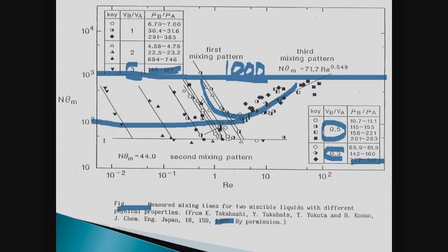It's 100 revolutions or 44 revolutions. So you're running at 1,000 revolutions, you improve your geometry. Now you're at 100 revolutions, and you improve your geometry again, you have 40 revolutions to mix. However, the rule of thumb, if you're looking for a rule of thumb, is anything under 1,000 revolutions you can mix.